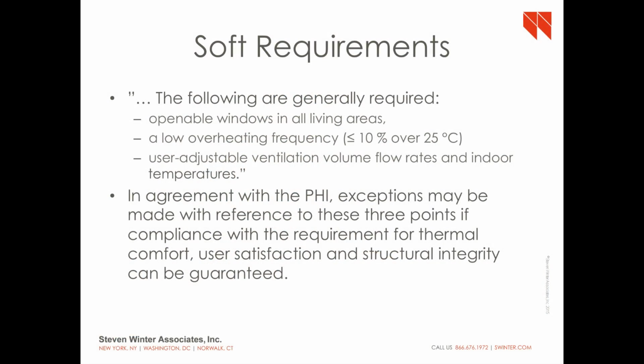These windows are a little controversial. Again, we tried to push, if we could meet our energy budgets, could we use a double pane window? But when we looked at the temperature of the surfaces and the condensation potential, we had to chuck them. So those condensation, comfort, durability, those are all the soft requirements I'm talking about. And there's a few there.